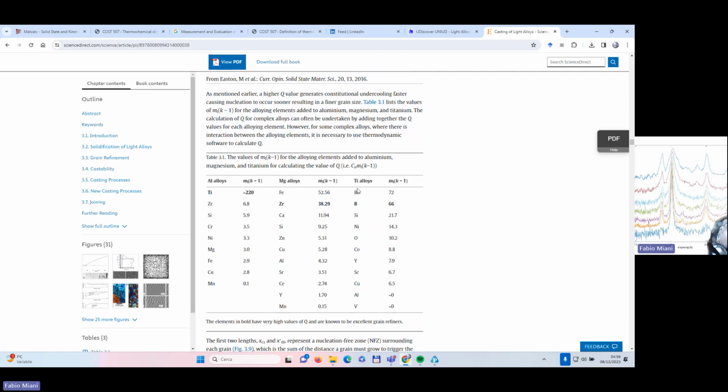for the moment, let us recall what we have just seen. So we will concentrate on this column, which is for magnesium alloys. It could be for aluminum, it could be for titanium as well. Now, these are calculations given a certain concentration in weight C0, given the M coefficient, which is available in the phase diagram, and this other coefficient.